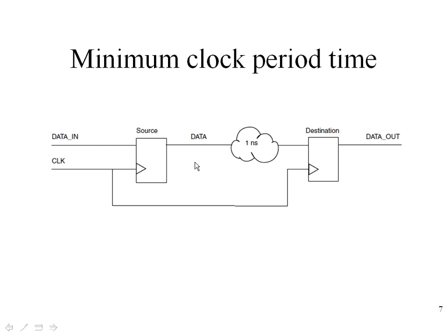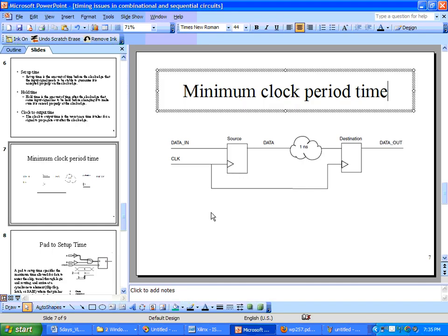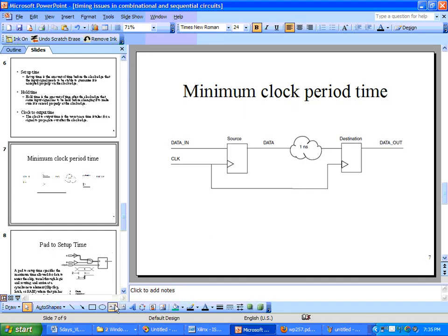See, usually in any big circuit there will be multiple register stages which are all driven by the same clock. The RTL design methodology demands that for whatever data path you want to maintain, the combinational circuit will come between register and register. Okay. Then in this case there is one equation that will tell what is the minimum clock period that is required. That is TCLK minimum.